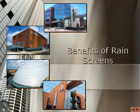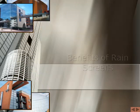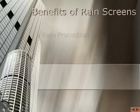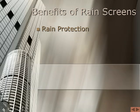Benefits of rain screens. We have already discussed the benefits of rain screen facades as it pertains to the prevention of water penetration into building walls. But rain screen facades also provide protection against moisture caused by means other than rain. Structural or domestic moisture is carried away via the air barrier. Thus, the function of the building insulation has a greater lifespan and considerably contributes to a more pleasant and healthier building environment.